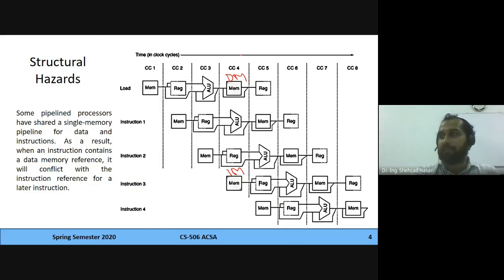Now let's come to cycle number 5. So we have discussed cycle number 1, 2, 3, 4 was problematic, but we have overcome that by using Harvard architecture, that is using two different physical modules. And if there are two different modules, then you can generate two different addresses as well from the CPU side, which are addressed to the two different physical memories. So one of them is going to data memory, and the other one is going to instruction memory, and so we can have both these tasks also happening in parallel. So everywhere where we are fetching, that's going to be changed to instruction memory, right?